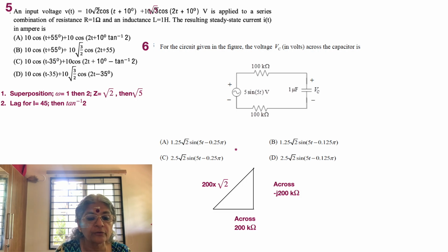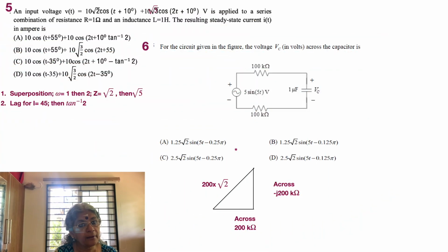Okay, and what is asked of us is the voltage across the capacitor. So for the voltage across the capacitor, you simply divide the voltage as a potential divider. But of course, it's a vectorial kind of division. Please remember that. Or in other words, 5 has now to be divided by a total impedance as given by 2.